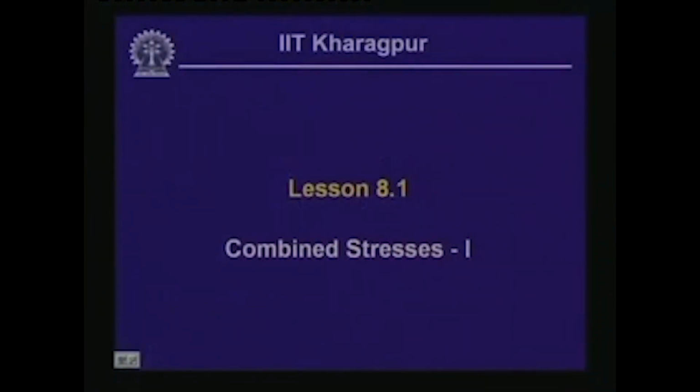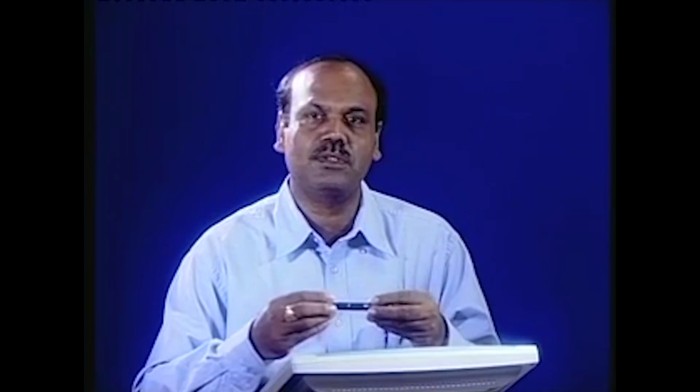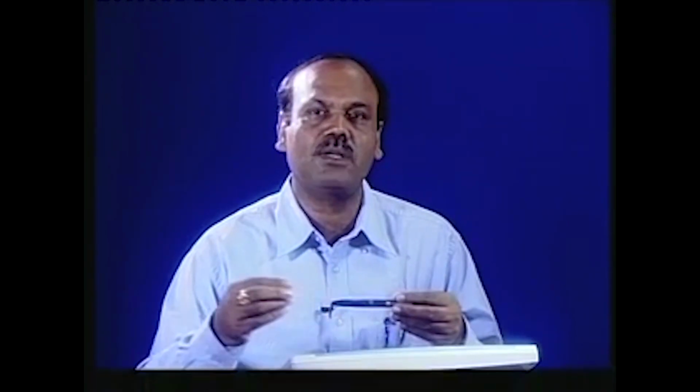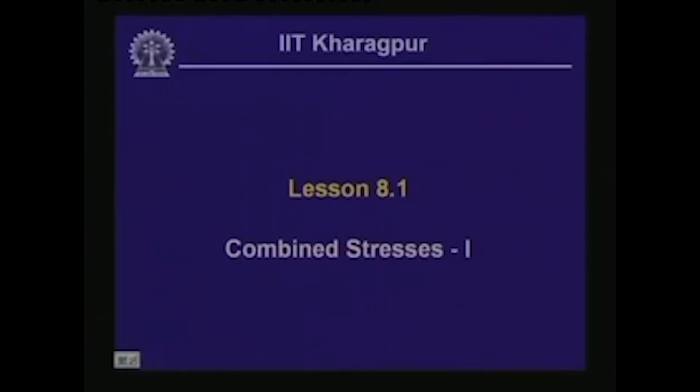Welcome to the first lesson of the 8th module, which is on combined stresses part 1, or more precisely let us call it the stresses which are developed due to the combined actions of loading in the members. In fact, so long we have discussed the action of different kinds of forces in the member which are acting in an individual form. Say for example, when we have discussed the axial force in a bar, the force was acting normal to the section, and we have computed the corresponding stresses, which we have called normal stress.